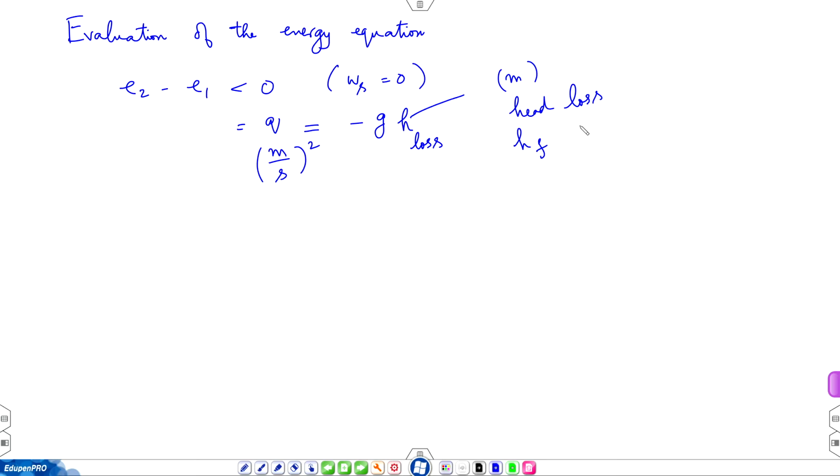Okay. So, let us say flow through a tube from 1 to 2, there is no change in velocity, there is no change in elevation. So, there is only a change in pressure. So, you have P2 minus P1 over rho is equal to minus g HF or H loss. So, this is now not an inequality, it is now an equation. Okay. So, if data is available to you on head loss, in some new application you can find the pressure drop.